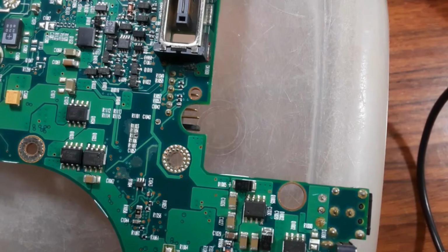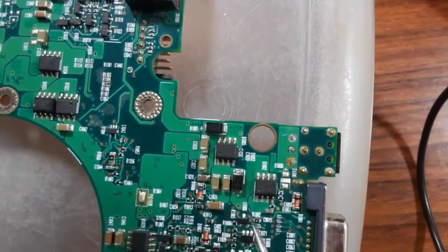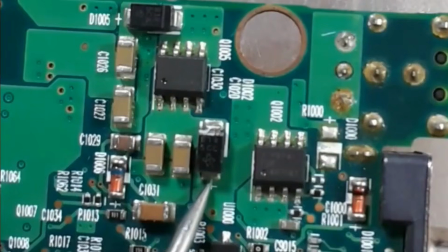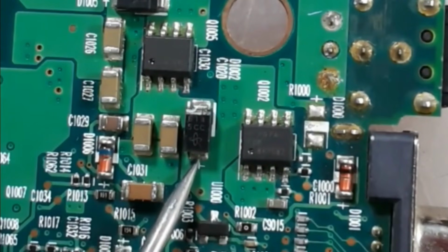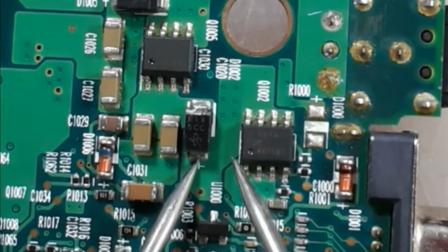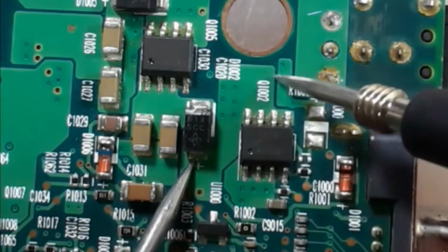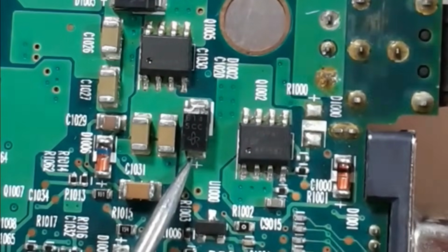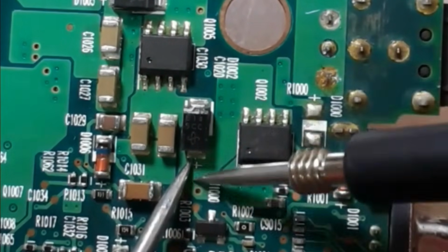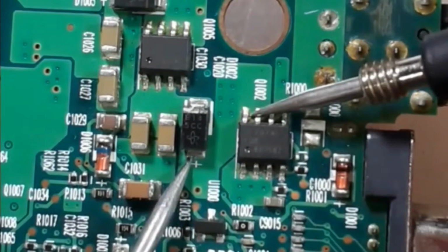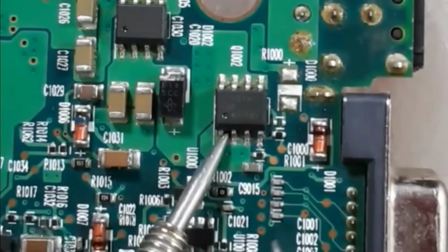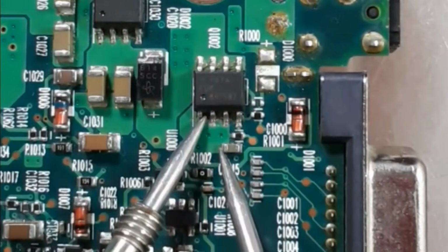Okay? For example, for this diode here, this diode is connected to what? To this? No. Here we have a bridge or another color. Let's follow this, as you can see. So it is connected here to the drain of this MOSFET, because we have here the same color, same path. Okay? But the source of this MOSFET is connected to this capacitor.